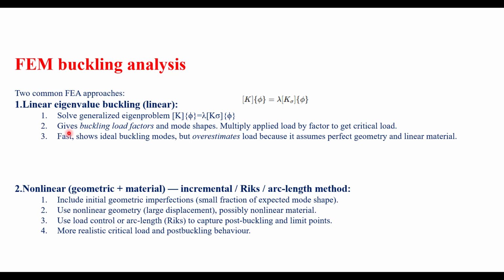We'll see that one. So what it does is it shows the buckling modes in a faster manner. Sometimes it overestimates, so that is why we say linear buckling is not that accurate. So for that we try to do the non-linear. It assumes the model is perfect geometry and a linear material, so it overestimates the loads. Okay, that is important. So don't believe the results of the linear buckling, in short. That is what I could recommend.